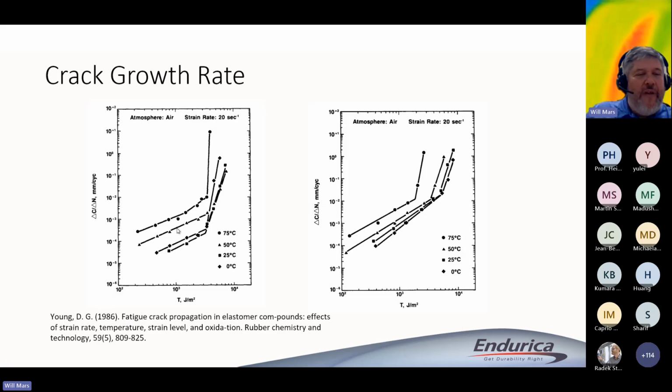It's kind of remarkable that if you look at the slopes of these curves, they aren't much influenced by the temperature, at least in these rows. So a common assumption, ideally you want measurements, but if you're not in a position to have direct measurements, it's usually a reasonable assumption that the power law slope is approximately not depending on temperature. So TC does depend on temperature, T0 doesn't, and F0 is maybe only weakly dependent.